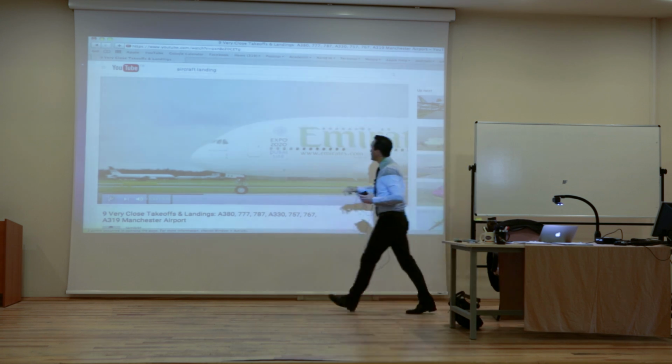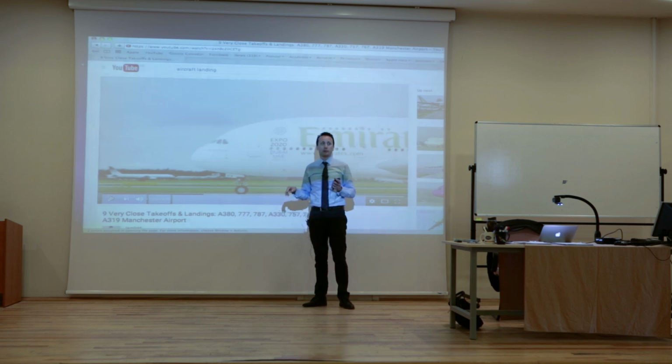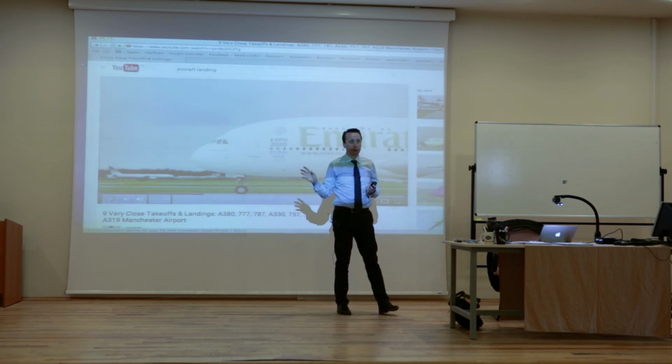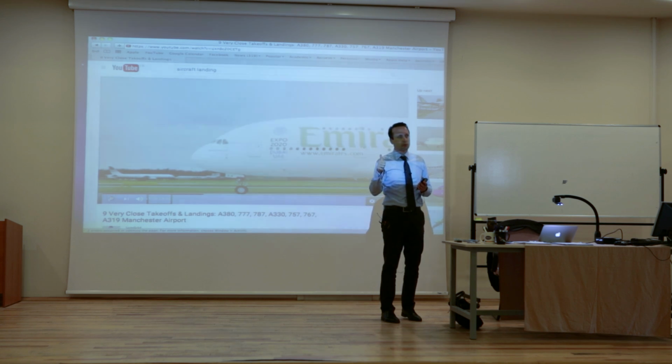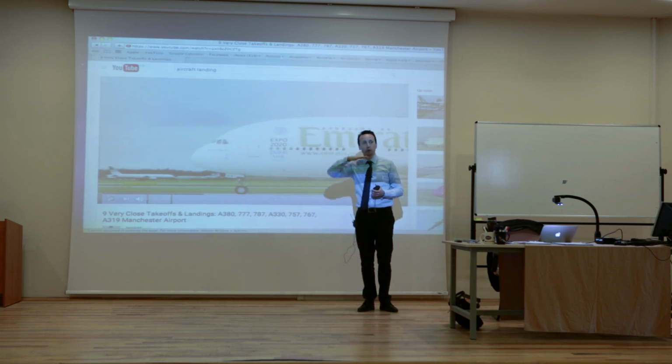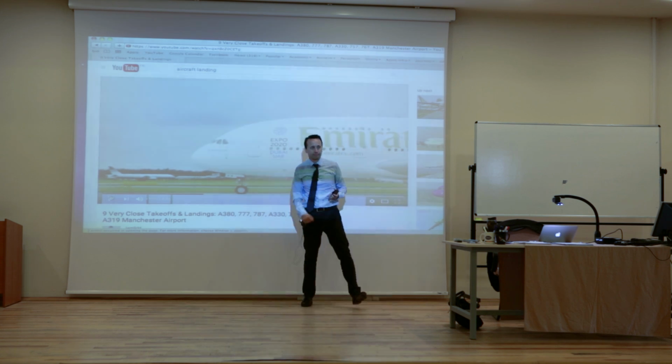What you're seeing here, there's more stuff, of course. There might be some other stuff. You're not only measuring V infinity. That's not only Pitot tubes. You also measure temperature. Very important. Okay? Temperature, V infinity, and sometimes these bigger airplanes also measure angle of attack. They have a little angle of attack measurement over here. Okay?